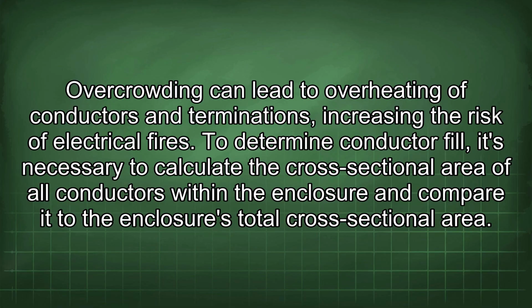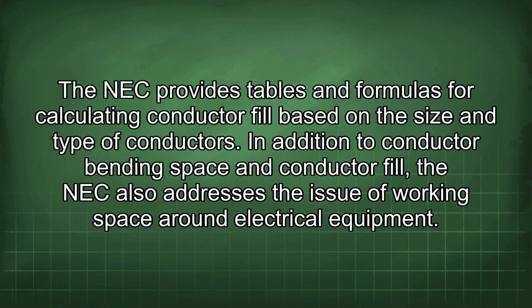To determine conductor fill, it's necessary to calculate the cross-sectional area of all conductors within the enclosure and compare it to the enclosure's total cross-sectional area. The NEC provides tables and formulas for calculating conductor fill based on the size and type of conductors.